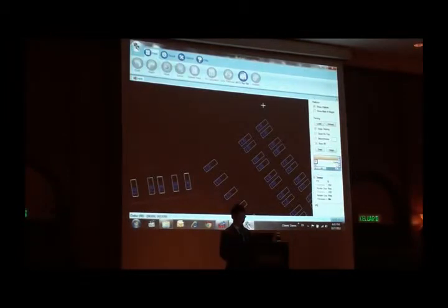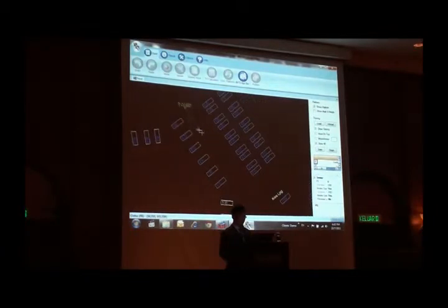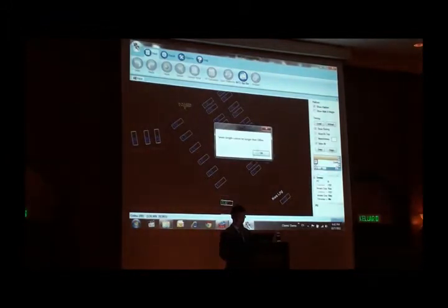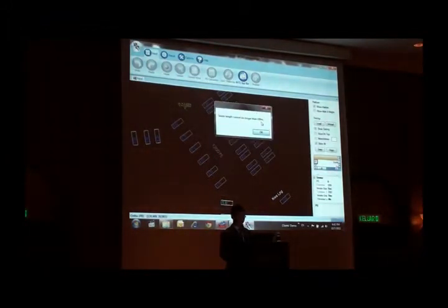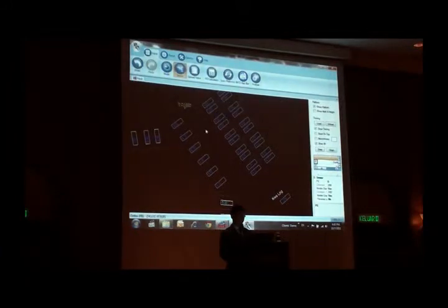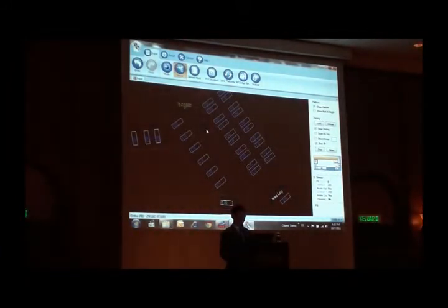Let's say I propose one manhole here, and go to the road. Then the software will always prompt us. Okay, this one, the length more than 100 meter. So this one we can preset. Let's say our sewerage length must not be more than 100, or maybe 30, some may say 30. So you can preset in the parameter setting, so the program will do internal checking for us. Okay, so just model.